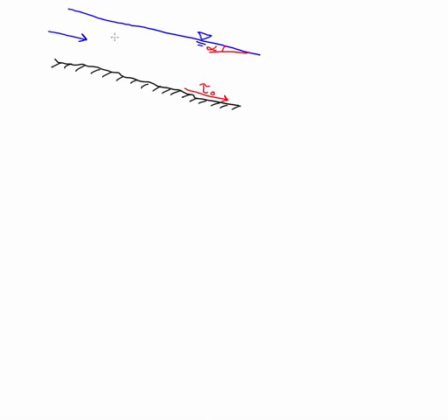The properties of this water in this diagram, right? Well, one, it has some water depth, d. And then the water has a density, rho, which has dimensions of mass over length cubed. And then we have gravity acting on that mass to drive the flow, which has dimensions of length over time squared. That's an acceleration term right there. So these are the things that are tending to drive the flow: the density, the gravity, and the depth of the water. And then clearly it depends on this slope here, all right?